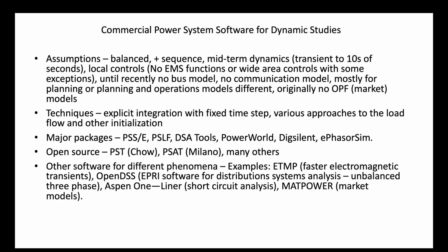That is a lot simpler to implement and it's more reliable. But if you remember, explicit integration is not numerically stable, meaning you're always going to get drift over time. That's why you don't really use these beyond about 20 seconds. It's maybe reliable a little bit longer than that, but you can't just let the program run for minutes and minutes of simulation time. There are various approaches to load flow and initialization, but fundamentally they're all the same.